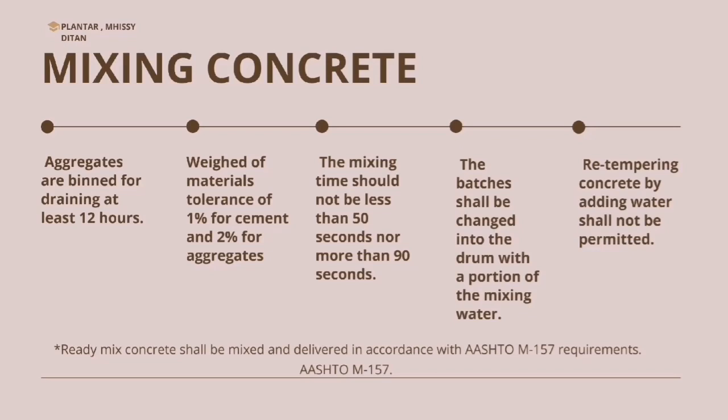Retempering concrete by adding water or by any other means shall not be permitted, except that when concrete is delivered in truck mixers, additional water may be added to the batch materials and additional mixing performed, increasing the slump to meet the requirement, if permitted by the engineer.